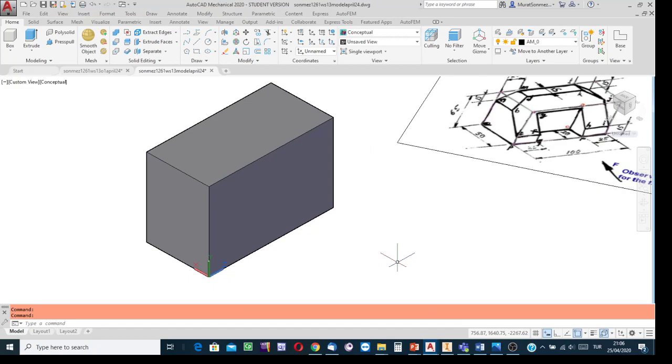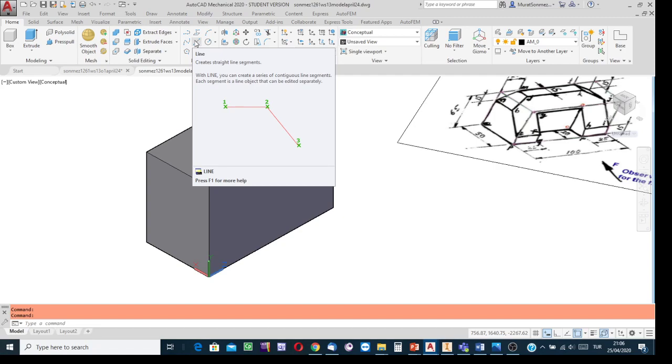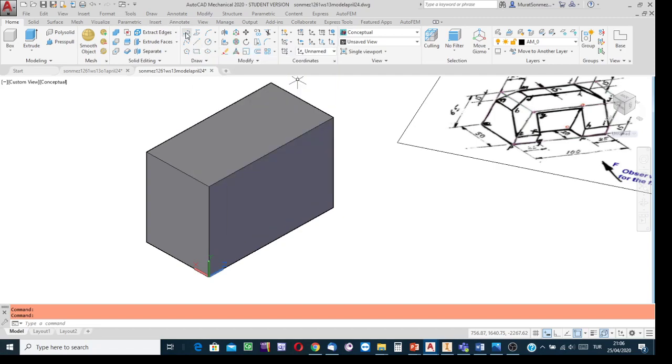So, to be able to have the edge view of that surface, start the line drawing process. Of course, to be able to have the profile as a region, for my convenience, not a single line but the polyline option. Select polyline, start the process. The terminal point corresponds to the image of boundary EF.